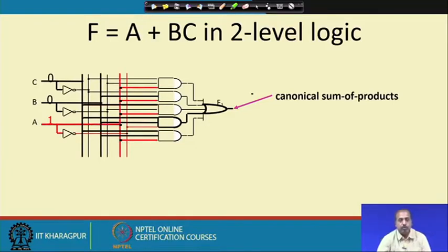So, this way, if you take these gate delays into consideration, you may find some behavior of these circuits in some intermediary form. Okay. So, that is not stable actually. So, in between it shows some glitch. Okay. So, that can happen. You can just trace through this circuit to see that this is changing the value. Okay. Whenever it is red, it means it is going to logic 1, and wherever I am showing it by a black line, it means it is at logic 0. Okay. So, you follow that convention and trace through these diagrams,